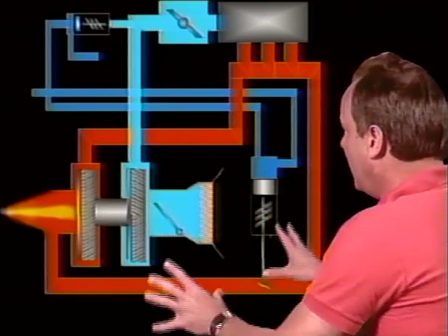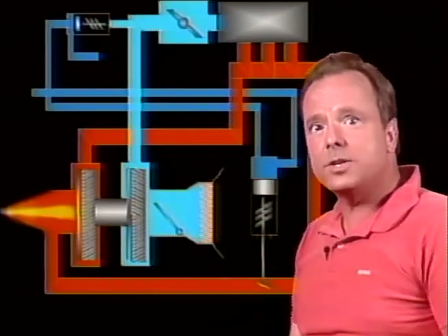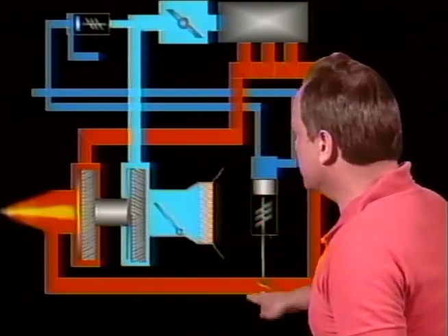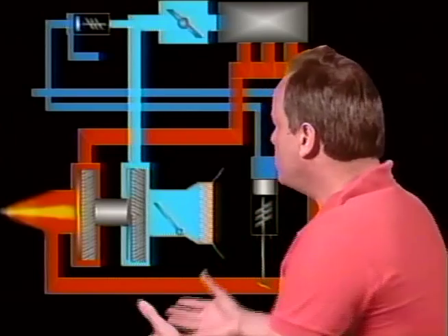All right, now let's take a look at a couple types of systems they have. One is a sea level boosted system, and we need to explain how the wastegate is controlled. We're going to talk about a sea level boosted system, and we're also going to talk about a turbo normalized system. The difference between those two systems is how the wastegate is controlled. By the way, the definition of a sea level boosted system is one in which you have boost on takeoff. In other words, more than 30 inches of manifold pressure on takeoff. It's called a sea level boosted system.